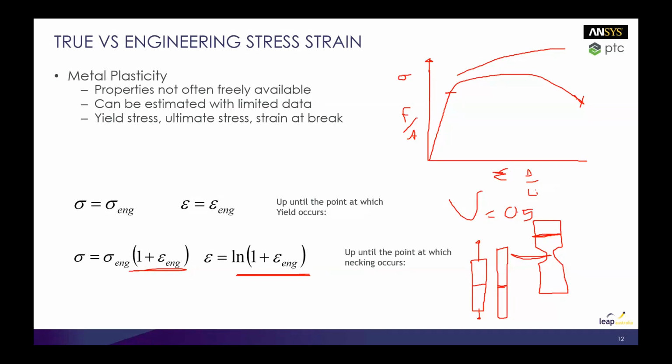When you make that correction to this stress strain curve, you don't get this negative slope. Essentially, the negative slope is saying that to keep increasing the deformation, you have to decrease the force. That doesn't really make sense. Whereas here, when it's always going up, to increase the deformation, you have to increase the force, which makes more sense.